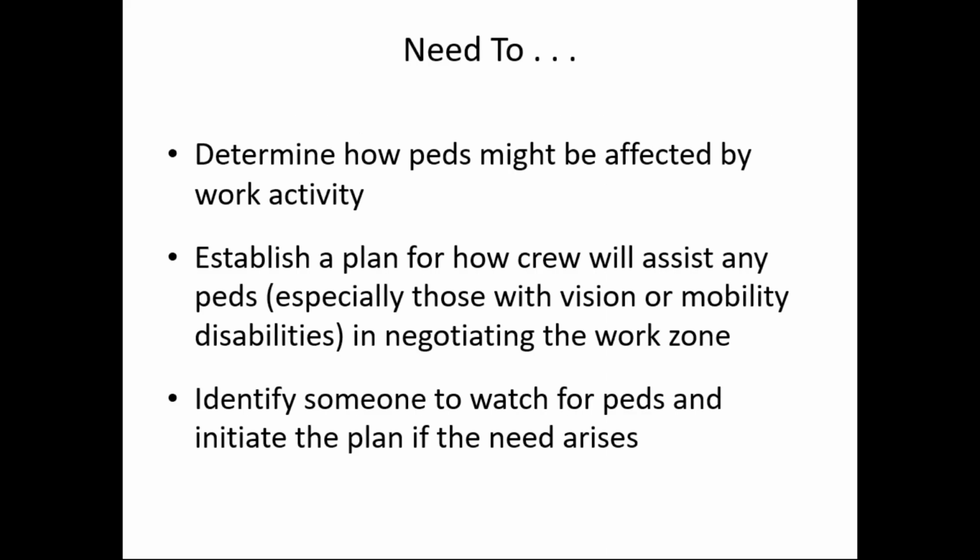So in that case, I would say, before you start work, determine how pedestrians might be affected by that work activity. And then establish a plan of how the crew is going to assist any pedestrians, especially those with vision or mobility disabilities, help them or assist them in negotiating the work zone. And then identify somebody on the crew to watch for pedestrians, all pedestrians, particularly those with impairments or disabilities, and then initiate the plan if the need arises.